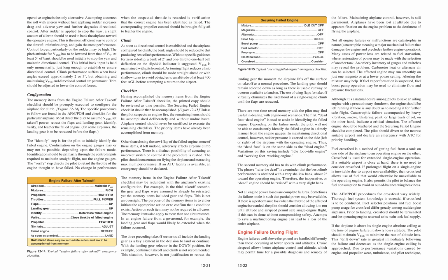The AFM/POH procedures for cross-feed vary widely. Thorough fuel system knowledge is essential if cross-feed is to be conducted. Fuel selector positions and fuel boost pump usage for cross-feed differ greatly among multi-engine airplanes. Prior to landing, cross-feed should be terminated and the operating engine returned to its main tank fuel supply.